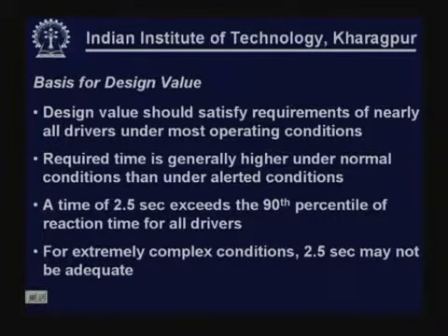One can justify that, that means if a 2.5 second value is taken, then that exceeds the 90th percentile of reaction time for all drivers. So, a 2.5 second reaction time is generally accepted for design purpose.